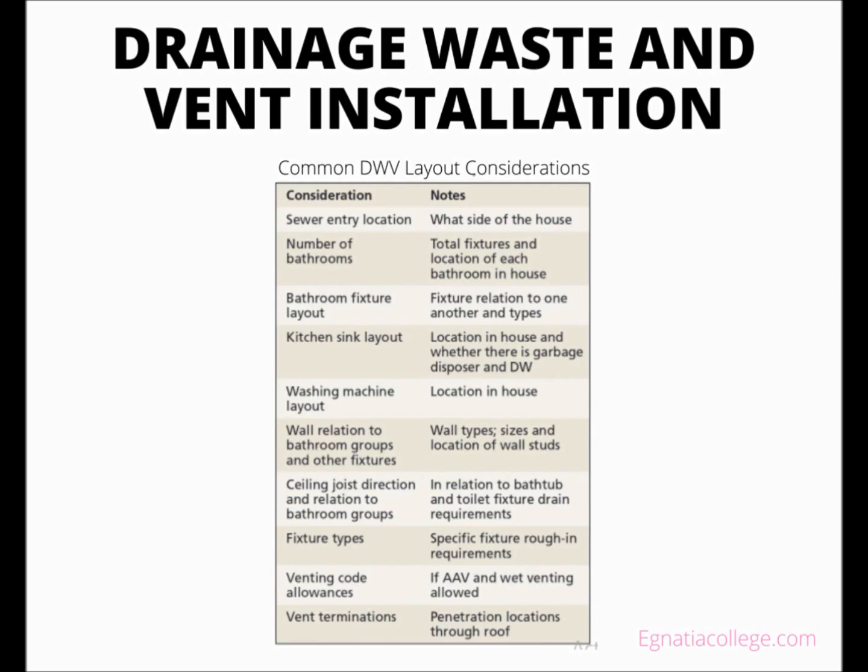If your local code allows wet venting, actual pipe routes are established for particular groups of fixtures. The fittings allowed by codes can also determine a pipe route, and the physical size of fittings can limit the chosen pipe route. Holes should not be drilled until the entire route is mapped out. This will prevent increased labor costs and eliminate unnecessary holes in studs and joists.